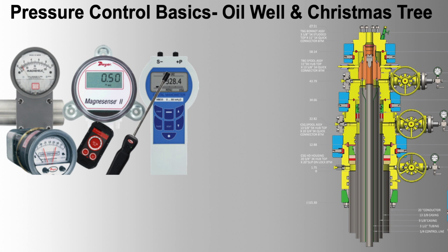Practical examples of issues and solutions. 1. Issue: instrument failure due to high temperature and pressure. Problem: standard pressure gauges fail at high temperatures and pressures. Solution: use quartz pressure gauges that are specifically designed for high temperature and high pressure environments, providing reliable performance and accurate measurements under extreme conditions.